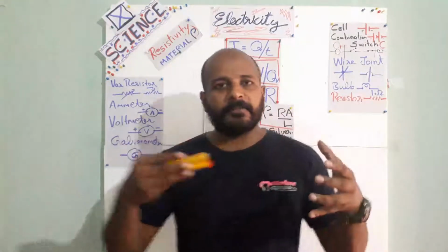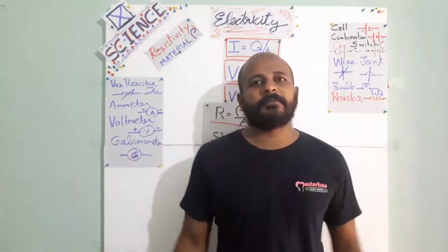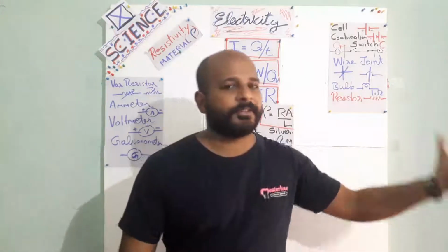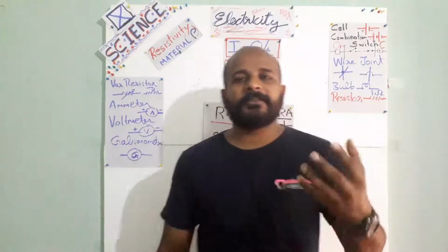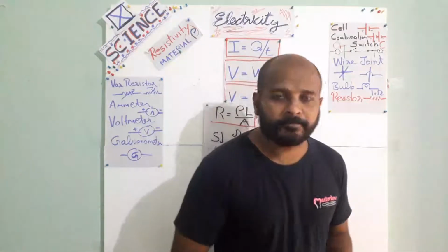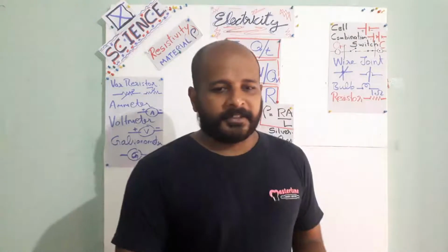Just imagine a wire is 1 meter, 1 ohm resistance. It is stretched to 3 meters. What will happen to the resistance? Resistance will increase. Resistance will become 3 ohm. What will happen to resistivity? Resistivity will remain the same. Isn't it? Yes. Okay, that's it.